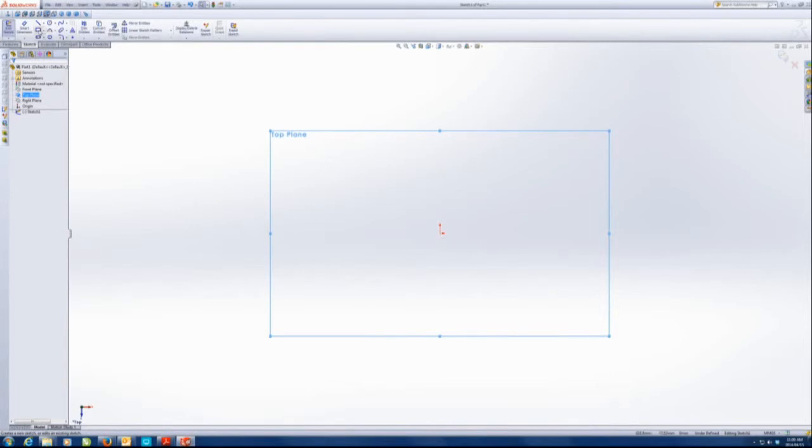So take the rectangle tool, and just by the way, if you have a look here, this is now the property manager for the rectangle. You can see there are 5 different types of rectangles we can draw. And for each one, you see there are numbers 1 and 2, 1 and 2, 1, 2, 3, right? Those are the clicks we're going to take to draw this rectangle.